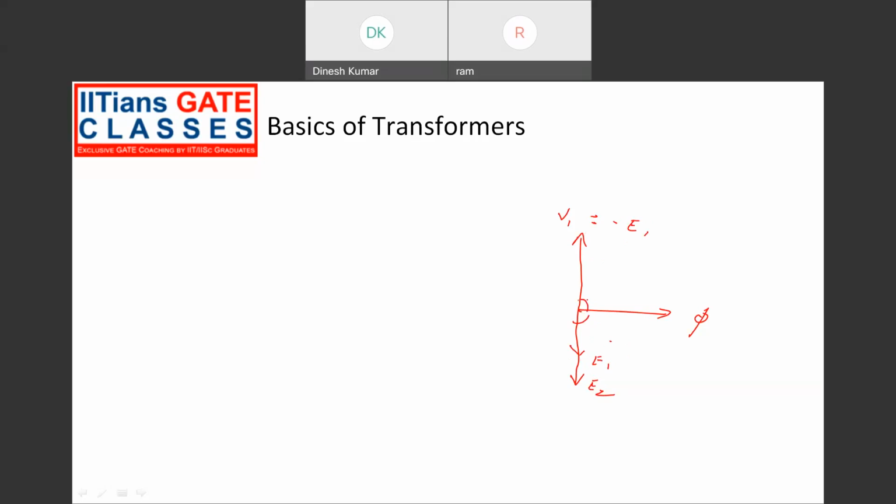This is a no load condition, meaning for an ideal transformer. If you take a practical transformer, it will draw some finite amount of current. Let's say that current we call the no load current. And this no load current is actually a combination or sum of two components. One is I mu, the other one is IW.